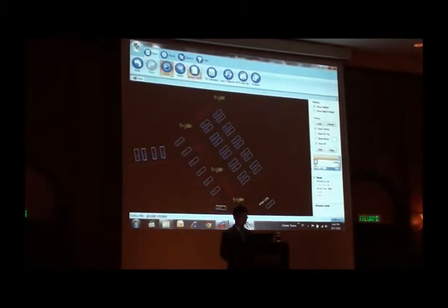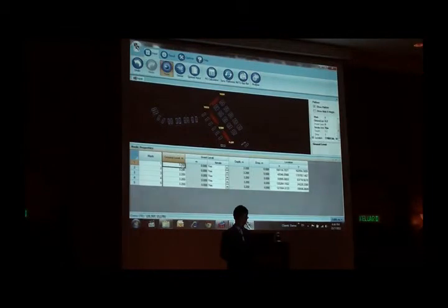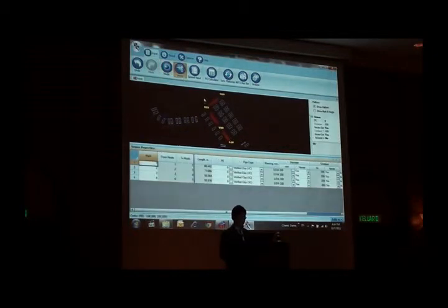So that's all. We go to the spread input. So the ground level is there. Maybe I just edit the last one, become 1.2 meter. Okay. And the invert level also is automatically calculated if we say the iteration is yes. Okay. Same as the depth and the drop. And for the sewer pipe,